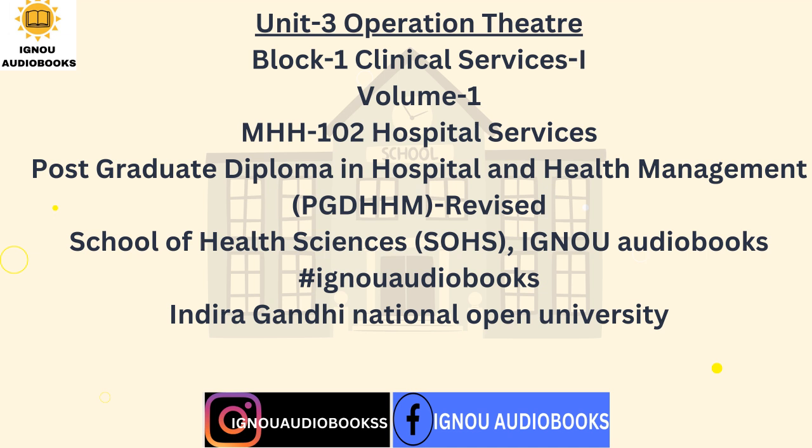Pendant. Pendant means hanging. Service pendants are ceiling mounted and provide manifold and electric outlets at convenient height for use. Oxygen, nitrous oxide, compressed air, and vacuum outlets are provided in the pendant. Electric sockets which are on UPS are also provided in the pendant. The pendant with manifold facilities is located near the anesthetist end of the operation table.